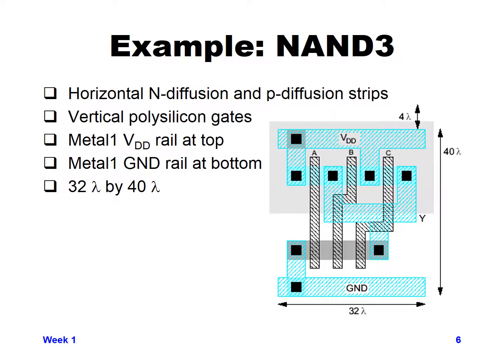So here, I just wanted to show a more complex layout than we've seen before, and we'll look at this in order to determine how large we would need to make a particular standard cell. We need to figure out what would be the X and Y dimension that you'll have to take up in order to design some of your more complex standard cells.